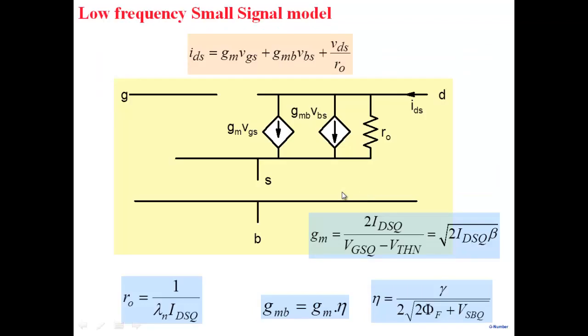All right, now whenever we talk about small signal approximation, there's always an issue of how small. Now remember, my MOSFET, like bipolar, is in general nonlinear in nature. So the small signal is always an approximation. The linear model is in fact never valid, strictly, because these devices are nonlinear. So when you approximate a nonlinear model with a linear one, there's always an approximation, there's always an error. And so the issue does arise as to how the errors change with the small signal voltage here.